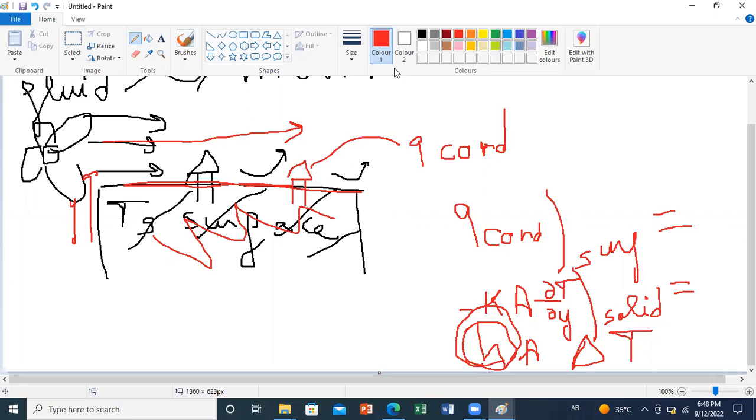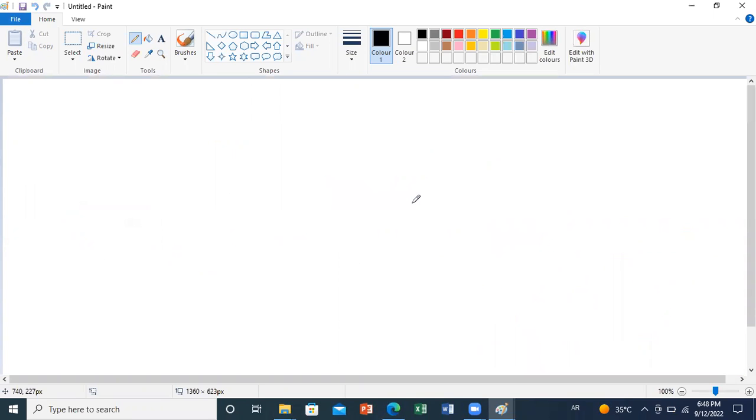Now, the third mode of heat transfer is heat transfer by radiation. The main difference with other modes of transfer is that we don't need a medium to have heat transfer by radiation, in opposition to conduction and convection. For conduction to happen, you need collision between molecules. For convection to happen, you need interaction between a solid and a fluid. However, for radiation to happen, you don't have to have a medium. You can just have an empty space. The only condition is to have surfaces at different temperatures.